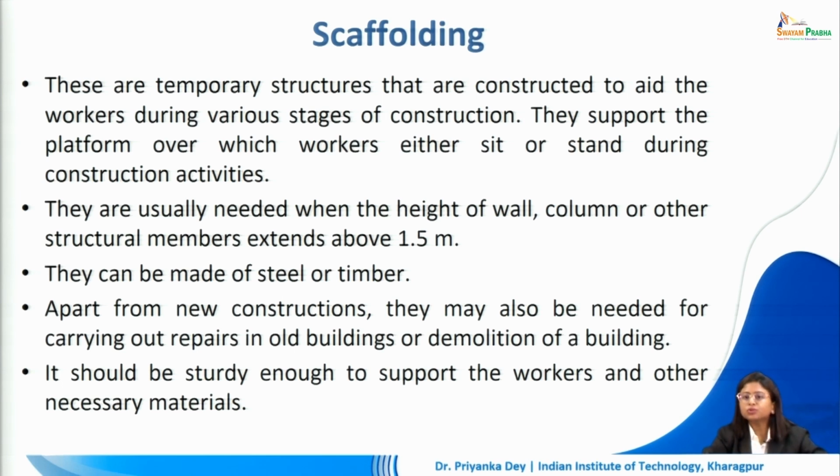It is very difficult to do so while standing on a ladder because we need a place to keep all our paints, our brushes, other tools that we need, and have a safe platform on which we can stand and work. That is where scaffolding comes into place. They are usually needed when the height of the wall, column or any other member that we are working on or constructing exceeds 1.5 meter in height. Scaffolding can be made up of timber or they can also be made up of steel.